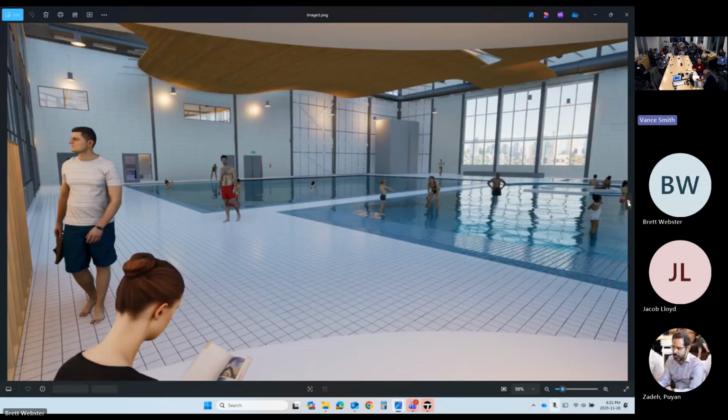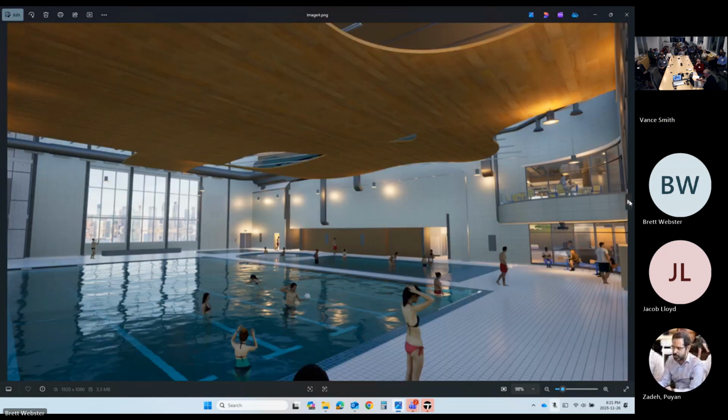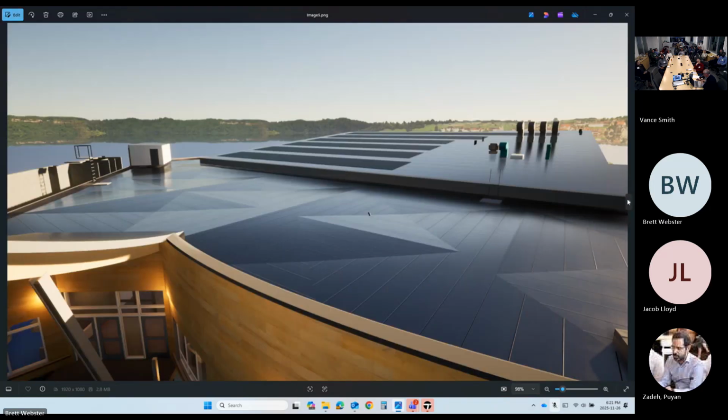So in Twinmotion, when we export to Datasmith, we can have a separate file, open that outside of Revit, and it's a standalone snapshot of the model at that time. Now you can add all your materials, and it's as simple as dragging and dropping in Twinmotion, whatever surfaces, like all these tiles, the pool water, that was just added as surfaces. And you can just drag and drop them straight on. Place all the people. Again, the lighting's come straight from the electrical model.